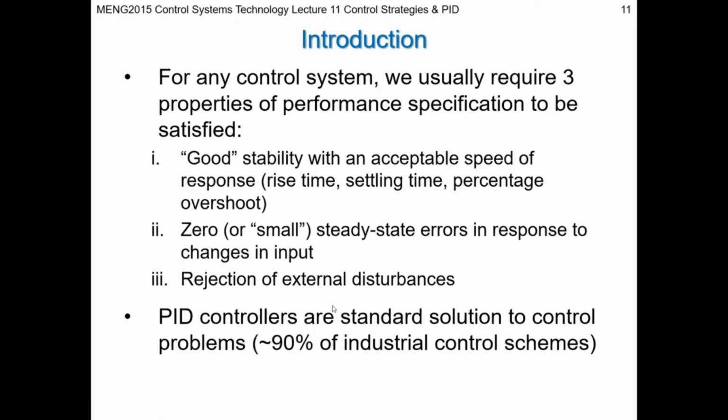So because we have a lot of process type plants, those tend to run in steady state. You want that plant just to run at a constant rate without any effects. So as that atmospheric temperature changes, if this process is sensitive to temperature changes, for instance, then you want any control system you have to reject the impact of that disturbance.